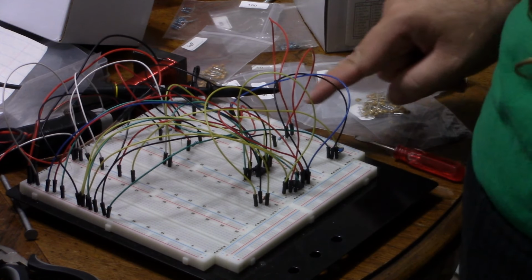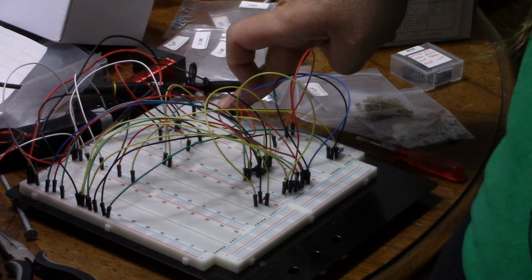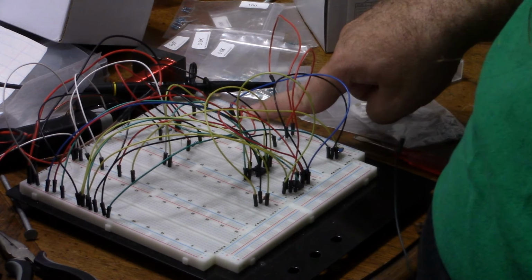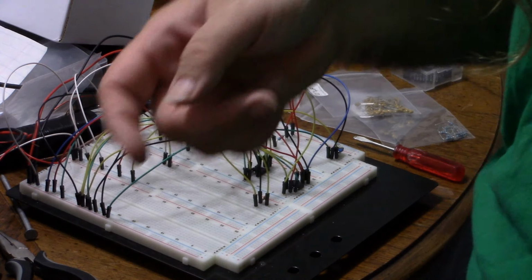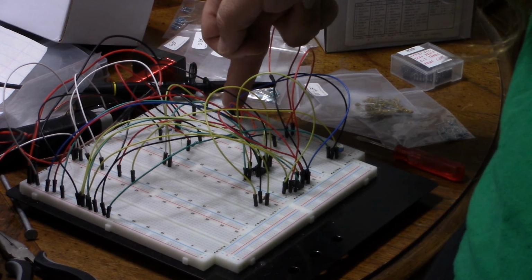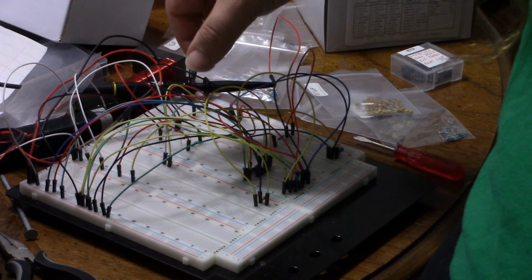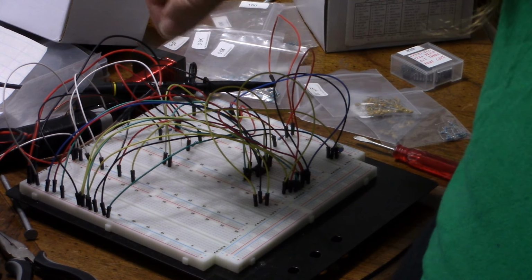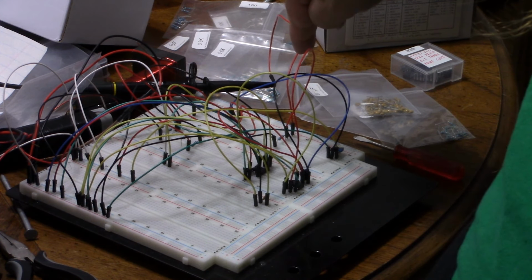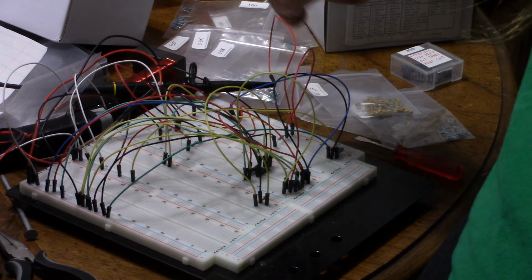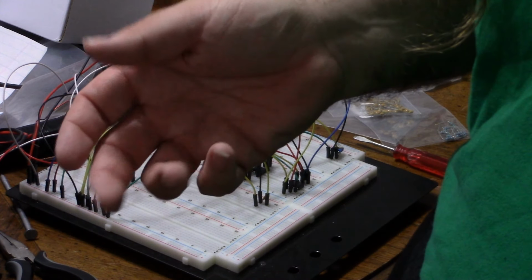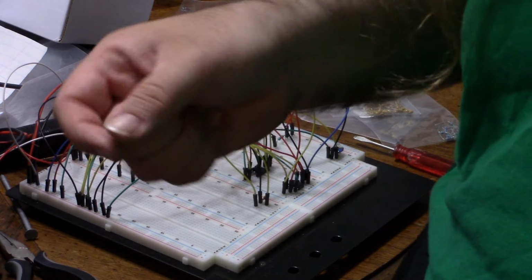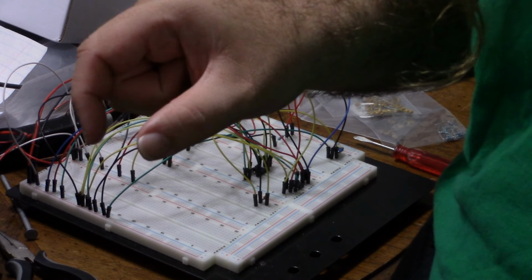The timing for the monostable is about a 3.9k ohm resistor and another 1 microfarad capacitor. The Texas Instruments datasheet recommended that the monostable RC network be about a quarter of the astable RC network, so the period of the square wave should be about 4 times the duration of the timer at normal voltage. It's just a guideline. You might have to fiddle with it a bit. These values seem to work for me. Just try a bigger or smaller resistor by a little bit if it's not quite working.